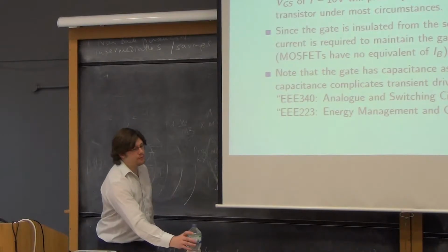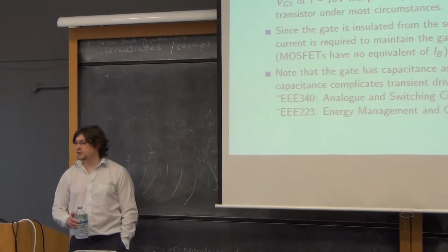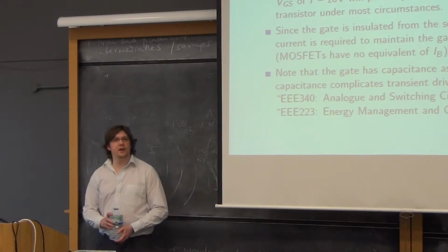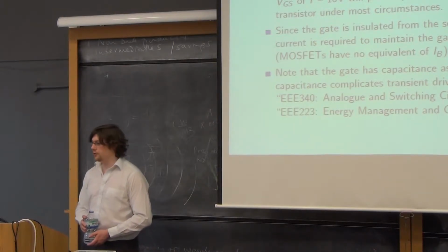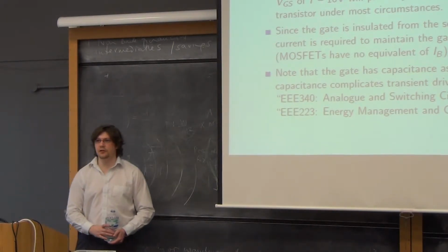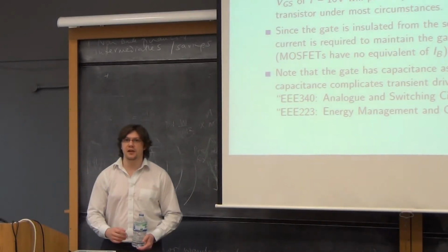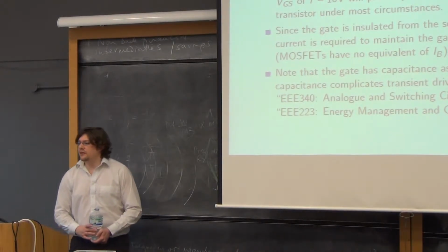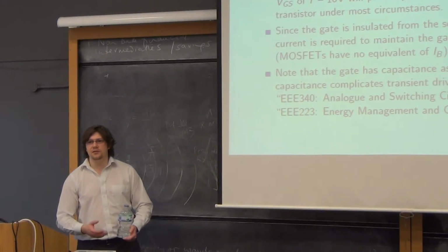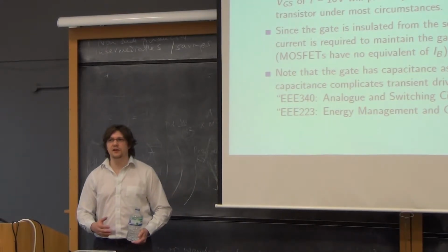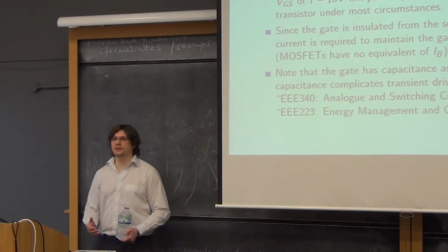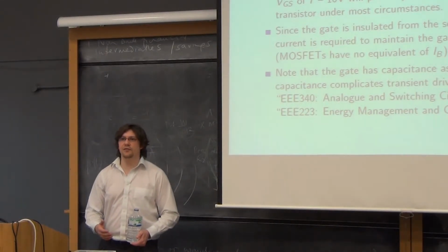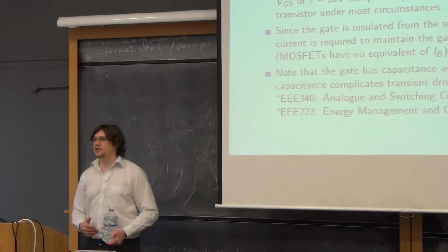So to ensure the MOSFET is fully switched on, the data sheet should be consulted. That's because there is no all-encompassing equation like there is for a bipolar transistor. So you'll have to have a look at the characteristics, that's to say output characteristics, and they will be on the data sheet. But in general, another rule of thumb, between 7 to 10 volts VGS will definitely switch most MOSFETs on. If it doesn't, you've got a very special one. And if you've got a very special one, I assume you've planned it, and therefore know what you're doing. So 7 to 10 volts, definitely enough.